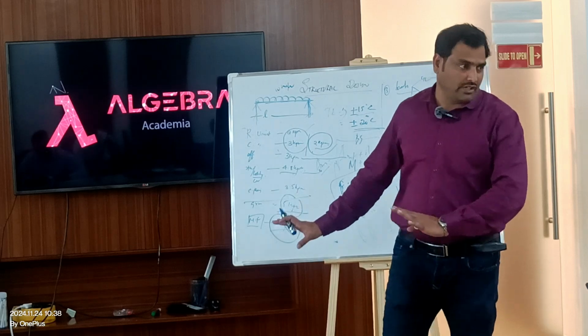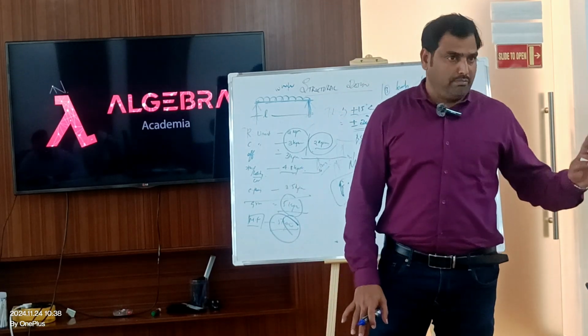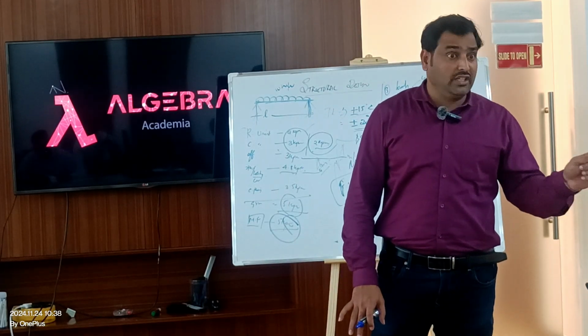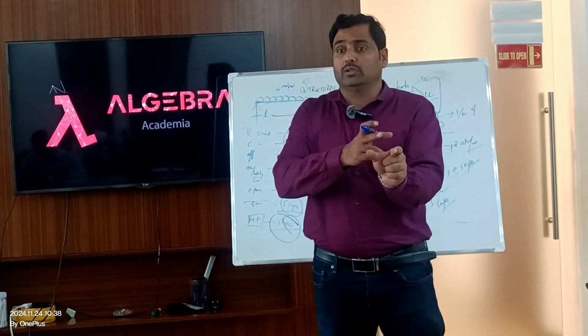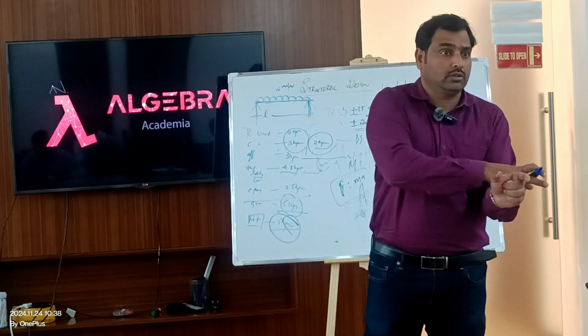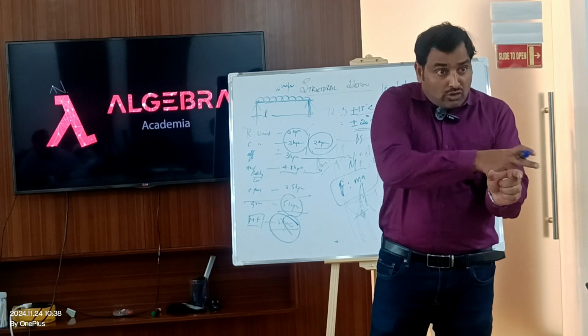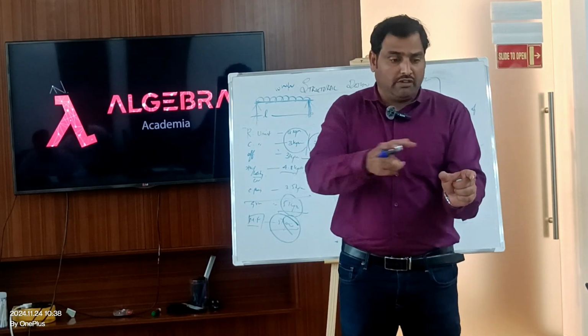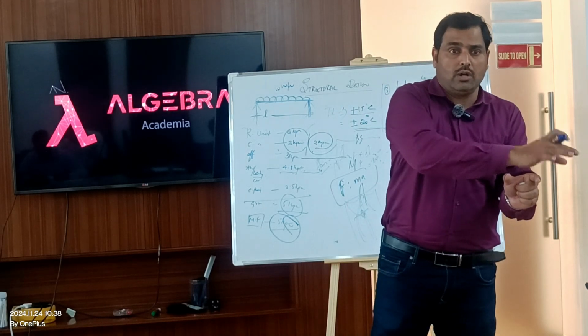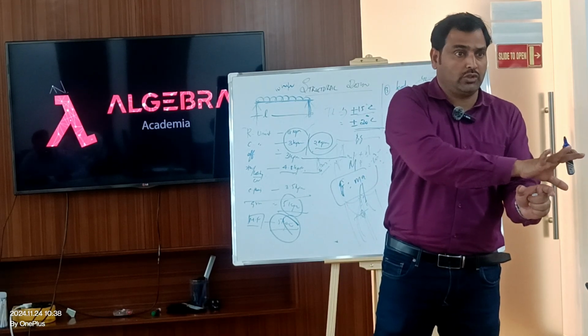You will never understand if I say it without basis. Based on the drift of the two, the drift defines the expansion joint width. The expansion joint width is defined by the drift. The length of the expansion joint is the criteria set by the code. But if you want to follow more than that, you can, but provide compensating reinforcement.